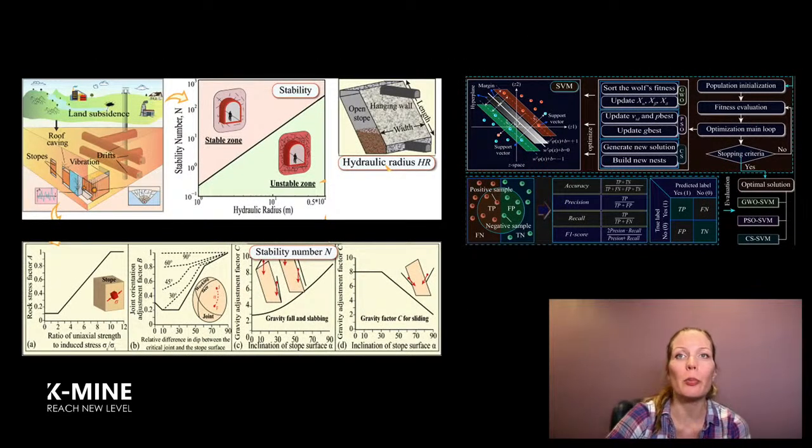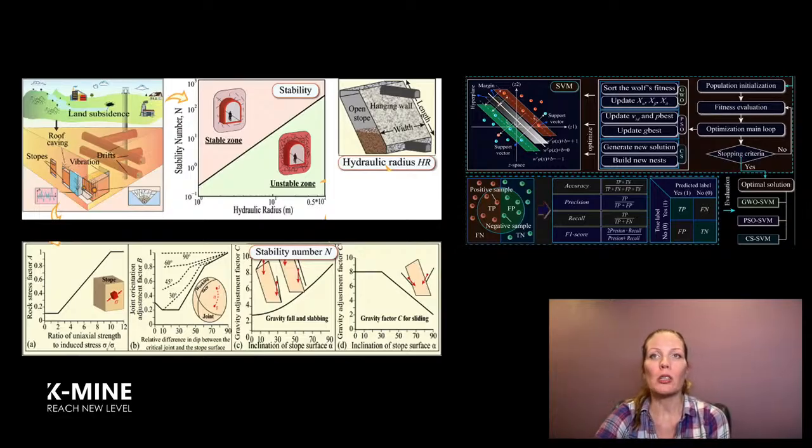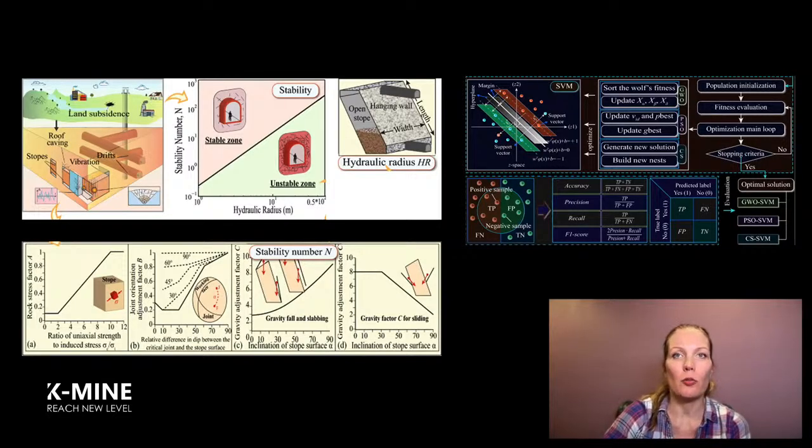So once the ore body is formalized and discretized appropriately for its type, the next step is to link the geometry to stability. Traditionally, this relies on the modified stability number and hydraulic radius, like the Matthews-Potvin framework, but instead of applying it manually during design, we incorporate it directly into the optimization workflow.